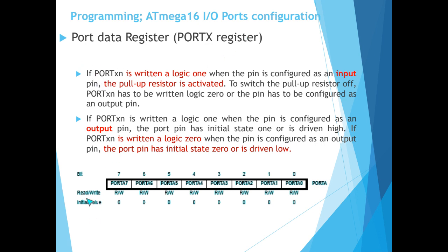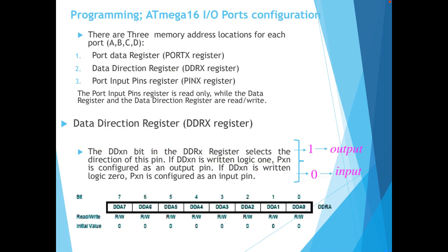We are talking about port A, and the code related to the port data register is written as PORTX. Here we are talking about port A, so instead of X, we replace A. This is the PORTA register. You see that? I wrote it here. And the previous one was the DDRA register.